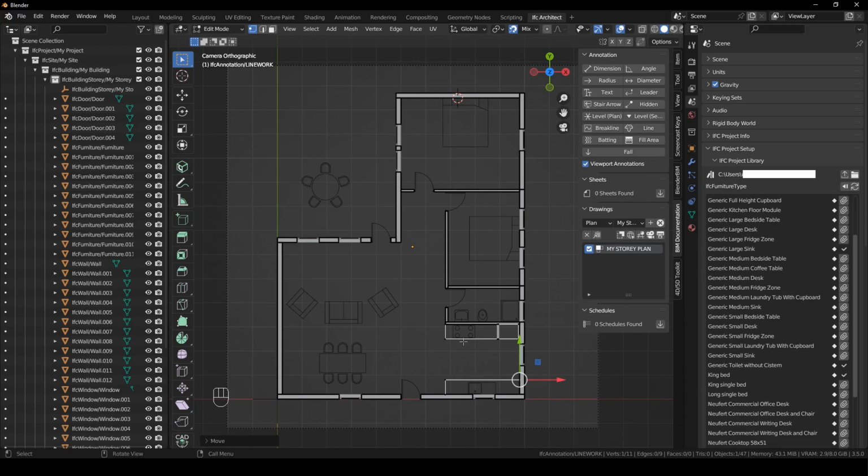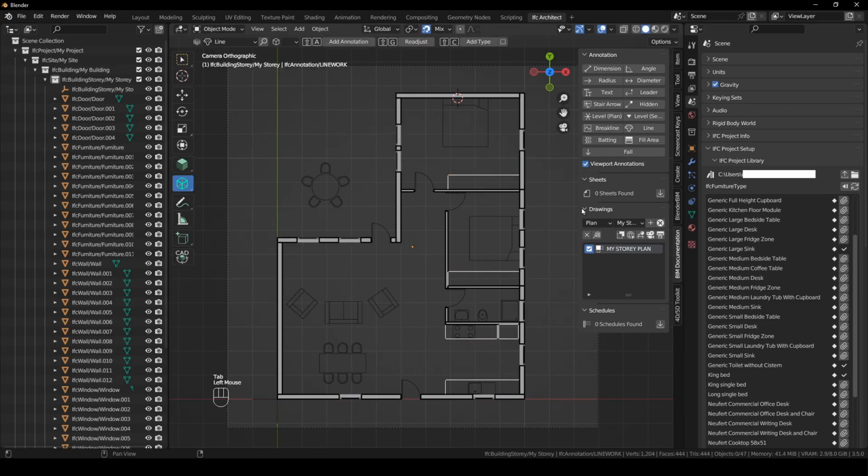So now we can do the built-in cupboards here. Just select this guy again and say Shift DY, snap it there, and then select these edges and snap it to the inside there. Grab this again, Shift DY, GY, there's some built-in cupboards, and that's all the 2D stuff we want to do for that.